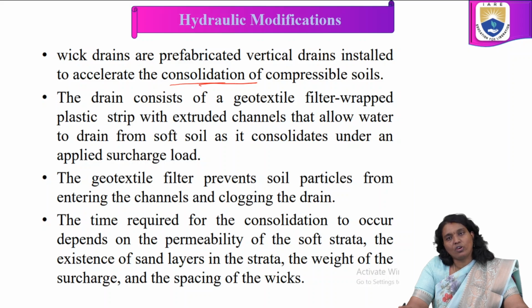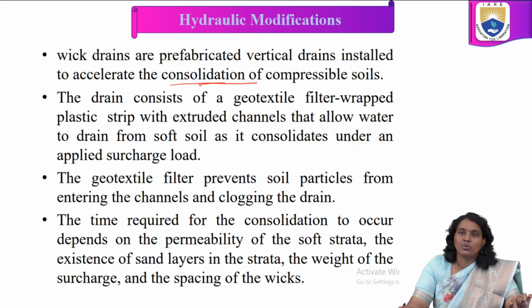Here also, based on the surcharge load, we use the required consolidation pressure, and we allow the water to flow into the filter wrapped plastic drain in geotextile format. The geotextile filter prevents soil particles from entering the channels and clogging the drain.